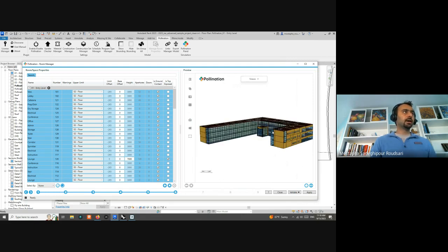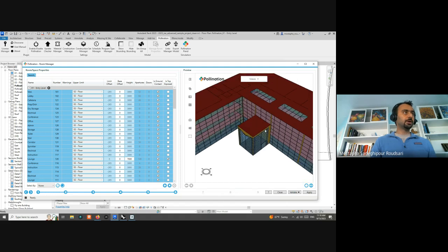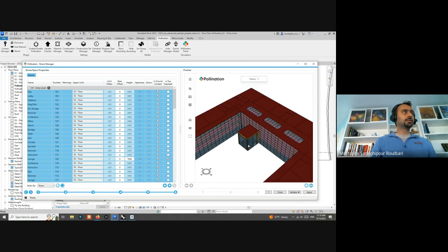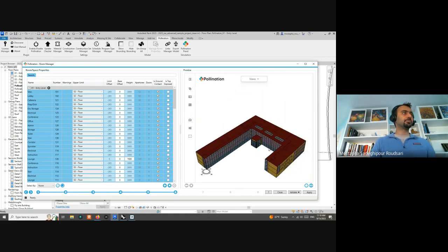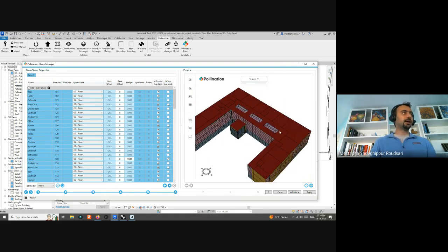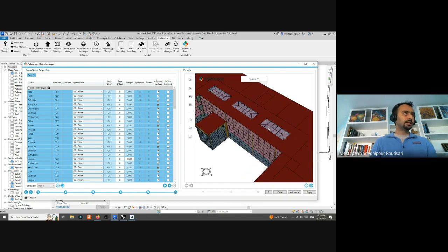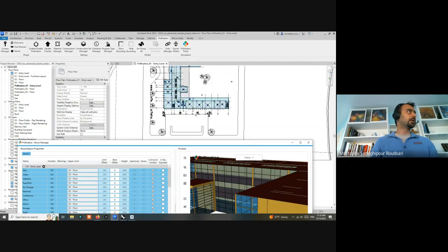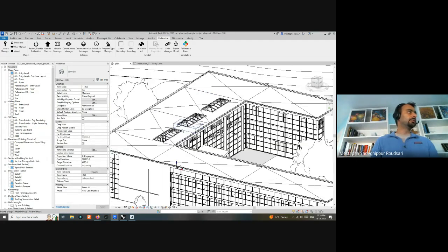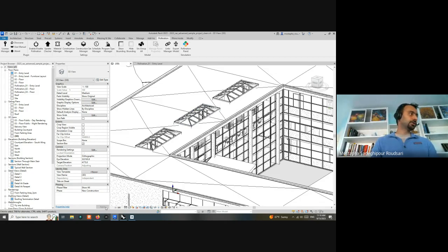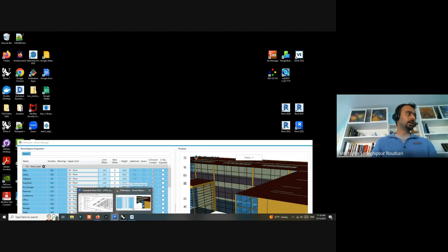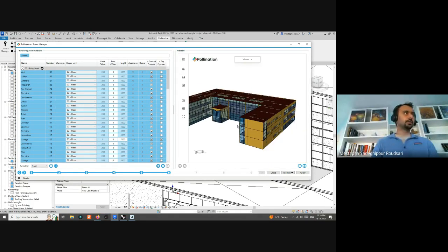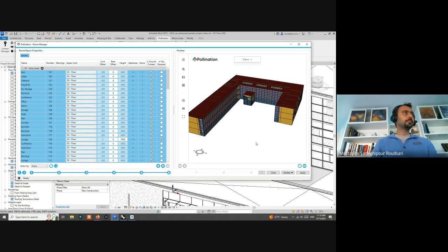All the windows. And if you know this model, you'll notice that this one is extruded because I used the extruded mode, not detailed mode. That's on purpose to show you more. And one other difference that we have here, because we are using extruded mode, is that these skylights up here are projected on top of the roof, right? In the real model, they're a little bit extruded. If you want to get them correctly, you have to use the detailed mode, but that will take longer. So I'm just going to use extruded here, and this is good enough for energy modeling purposes.